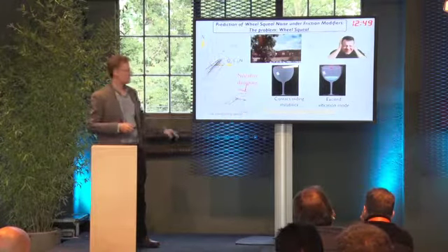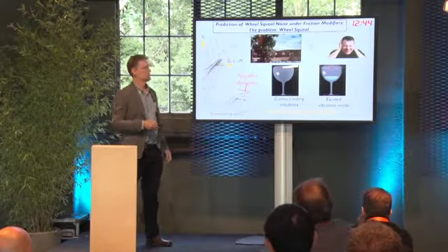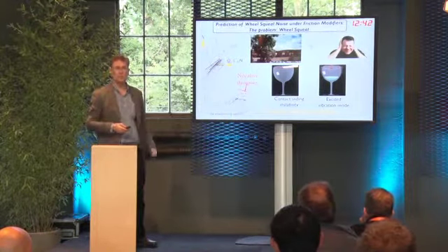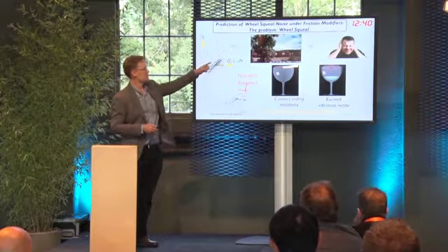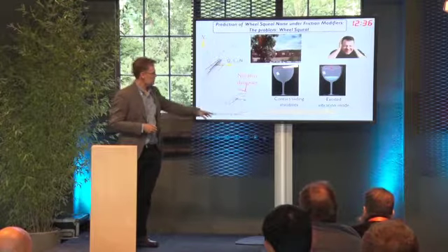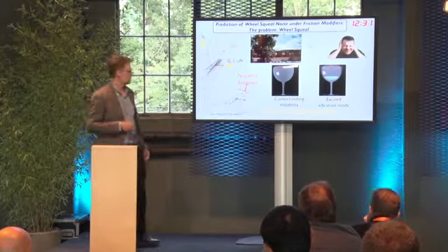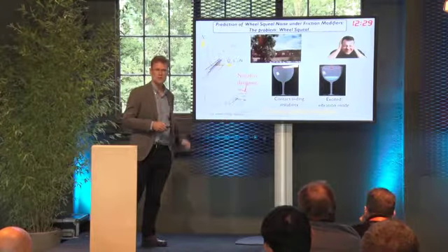And the conventional mechanism is that the falling slope of this creep curve introduces power input and excites this mode in a similar way to a bow exciting a violin string at the natural frequency of the string.